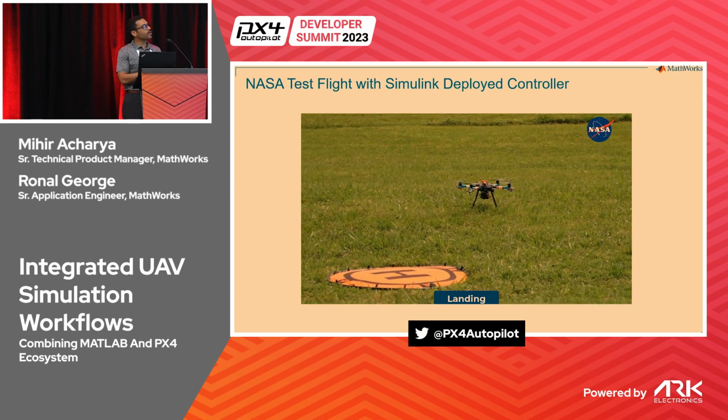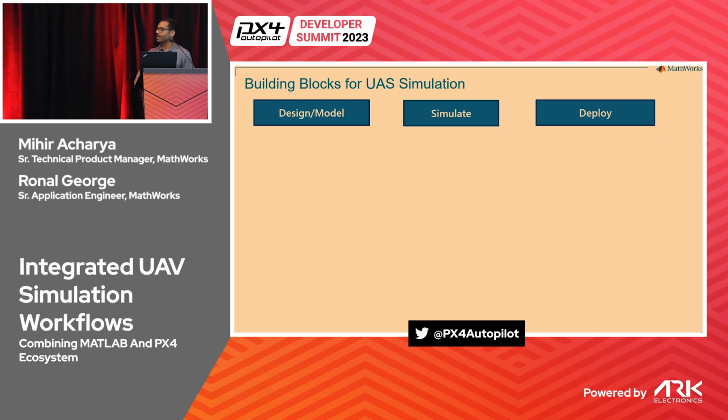But they started with the quad rotor and eventually want to go to custom platforms. The capability that you get here is your control laws can be deployed directly onto PX4 using MATLAB and Simulink. So be it you have a tail sitter, or a fixed wing with 14 servos, you can build the controllers directly from MATLAB and Simulink and deploy it onto a Pixhawk or a PX4 board. Yeah, I'll let Mihir go through and I'll talk about an example later.